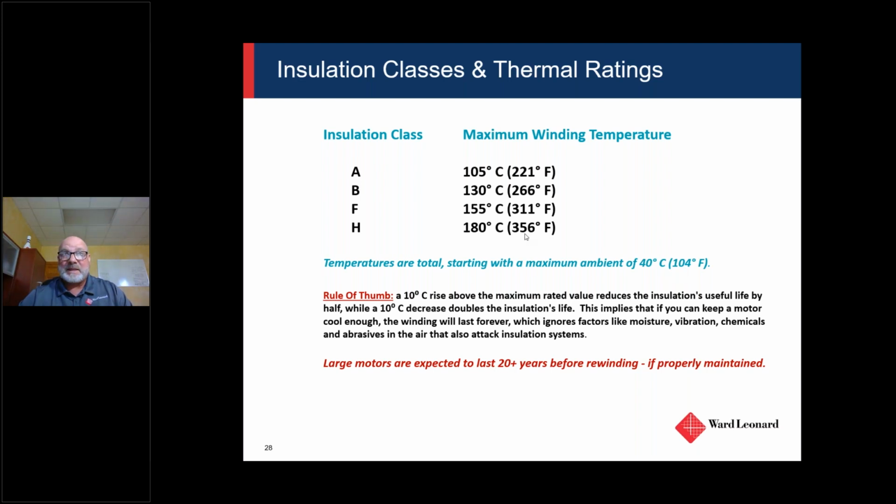In order for it to be a Class H motor, every component in the motor, from the electrical aspect, not really mechanical, but the lead wire, the insulating materials, whether that be your slot liners, your wedges, your sticks, your phase paper, anything you're using in there, needs to be rated Class H. If it's not, then it's not a true Class H.